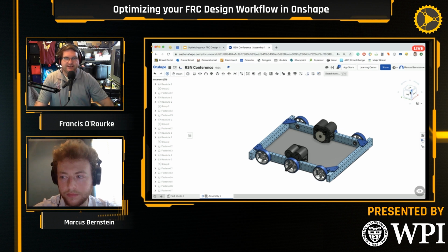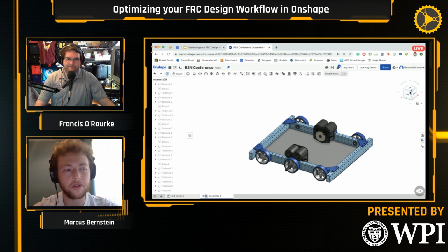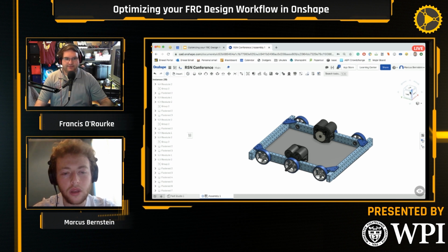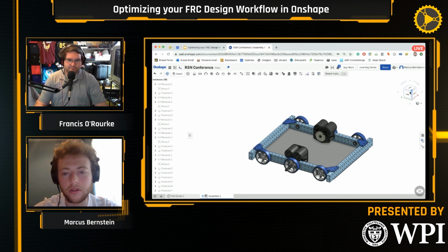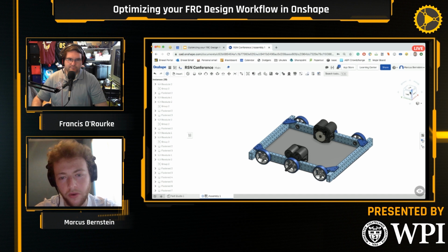And so for those things, you want to double check, optimize, or just make a more generic model if you can get away with it. Definitely. I would also advise hesitation to work with STLs or other mesh models within Onshape. Yeah. Onshape is designed around parametric stuff, and so pulling in the step, pulling in a SolidWorks part, pulling in that stuff tends to be very easy.